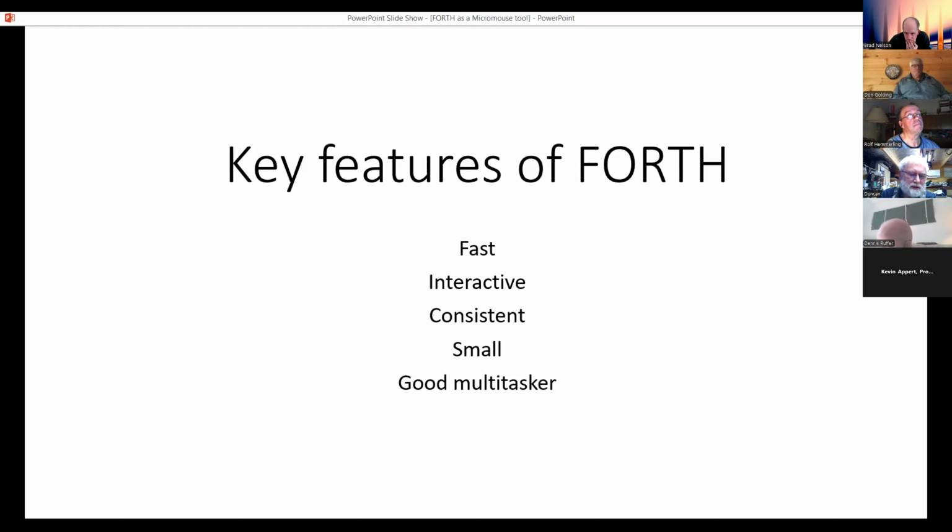I sometimes use interactivity over Bluetooth while the mouse is running. So I can have a task talking to me over Bluetooth on a terminal, while the rest of the mouse is running in other tasks. So the mouse is zipping around, for example, a line follower course, and it's doing a control loop where you've got speed and a proportional control constant and a differential control constant. And via the Bluetooth, I can change those interactively.